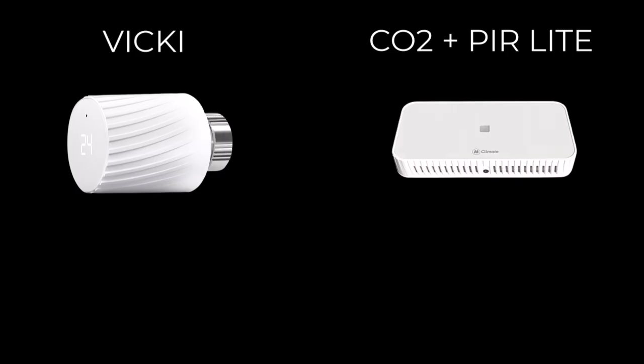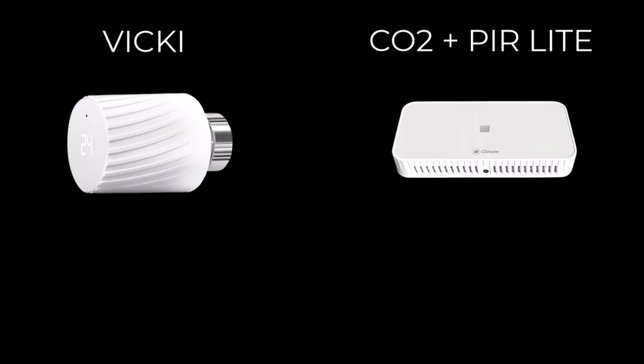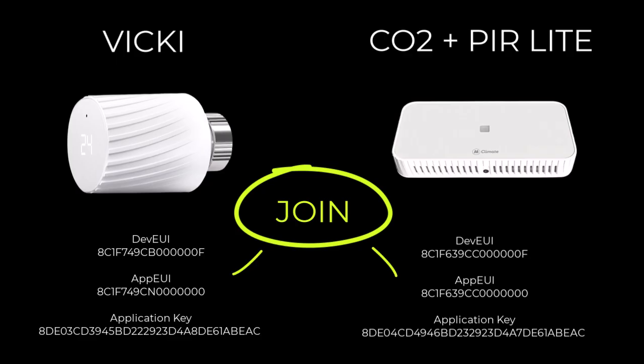In this example, the first step is to connect two sensors to the Watsense box. The sensors are Climate Vicky and a CO2 plus PIR light. For the sensors to communicate with the box via LoRaWAN, a join procedure is required. To perform this procedure, you will first need to obtain identification numbers specific to each sensor. These identification numbers are provided by the supplier.